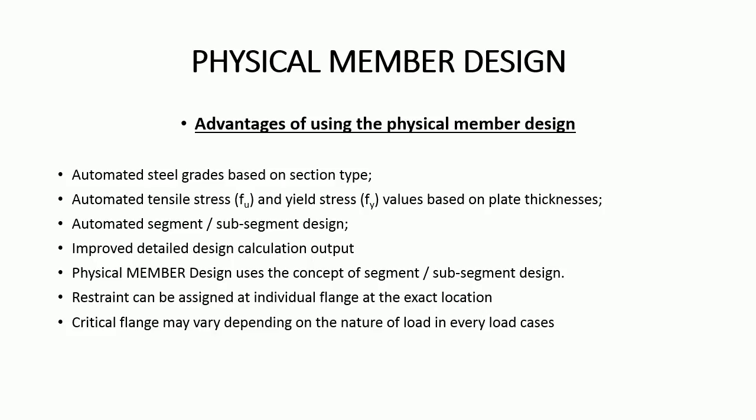Now, STAAD can identify this critical flange depending on the direction of the loading condition and the assigned restraint along the physical member length. So in a nutshell, we strongly recommend following the physical member design approach in STAAD.Pro rather than the analytical member design approach, as our development team is more focused on the enhancement, development, and rigorous testing in the physical member design mode as far as the AS4100 code implementation is concerned.